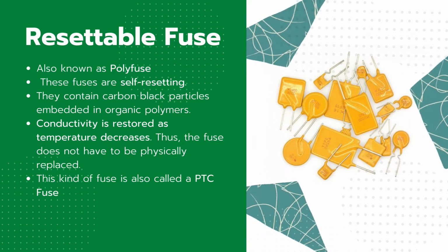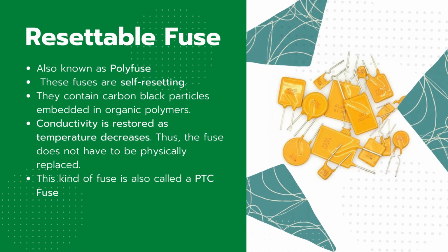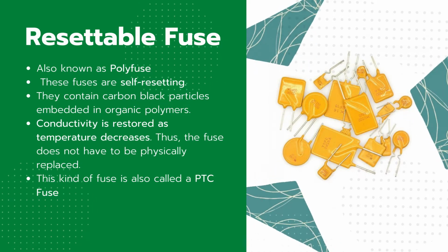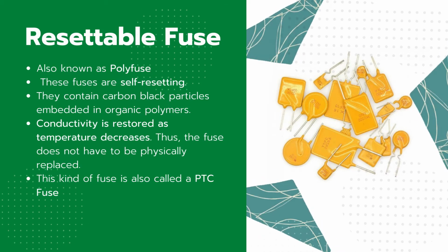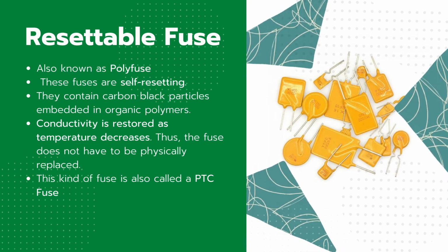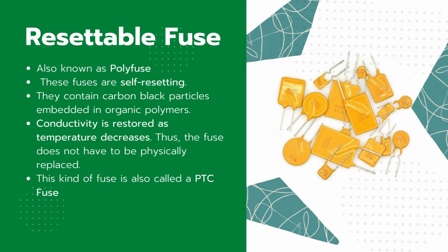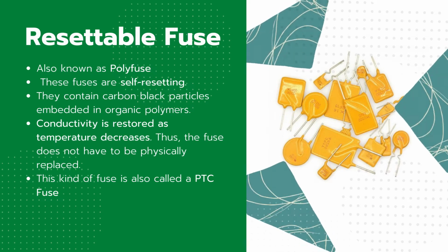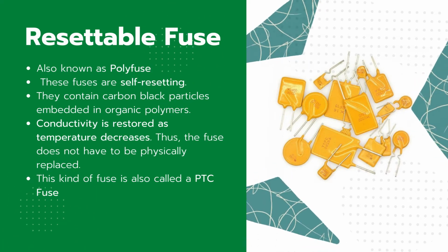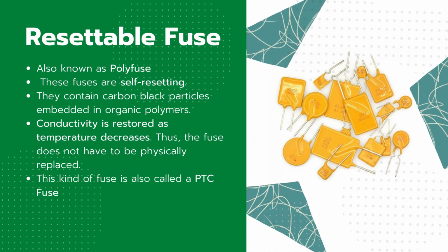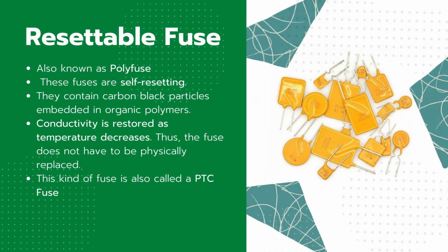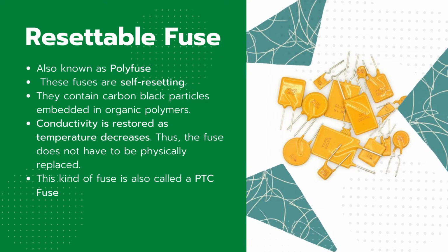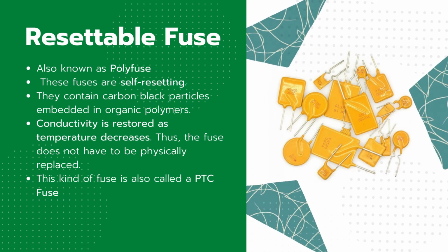This kind of fuse is called a PTC, meaning positive temperature coefficient, since resistance increases with temperature. PTC fuses are ubiquitous in computer power supplies and phone chargers. They are particularly handy here since replacement is difficult. For the same reason, they are used in aerospace devices.